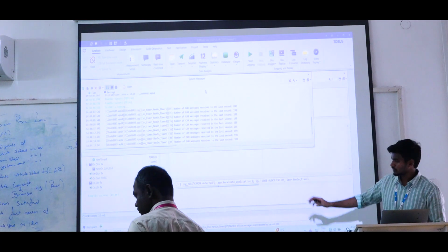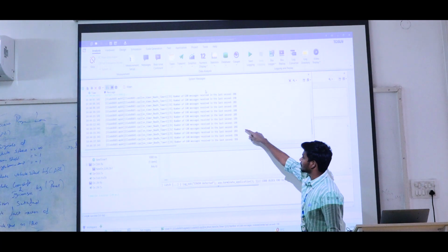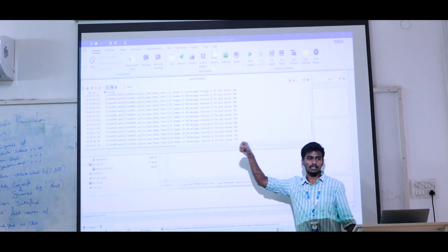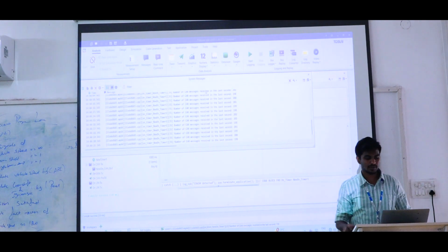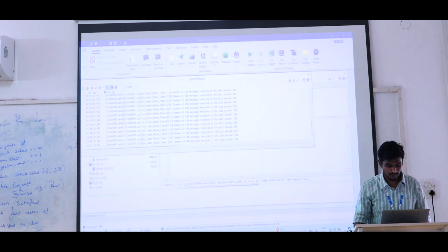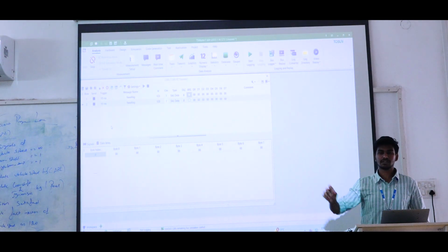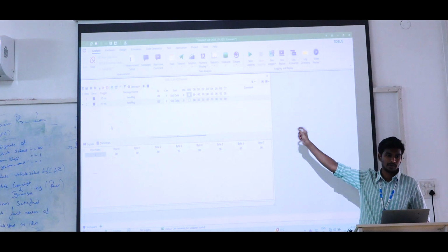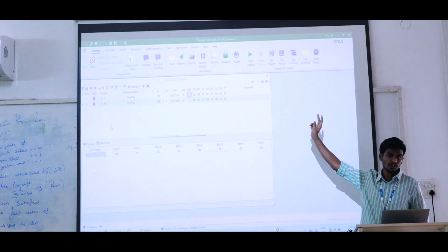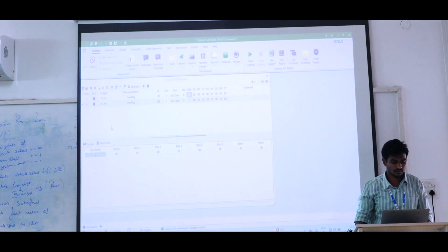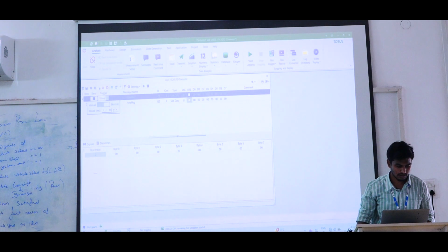So last second, if the values vary from 198 to 102, it means this many messages, because we are using the FPS of 10. Cyclic message time of 10. So per second, 100 times we transmit per message. So two messages transmitted 200 times. Got it. For example, if I am changing one to 100 milliseconds, it means